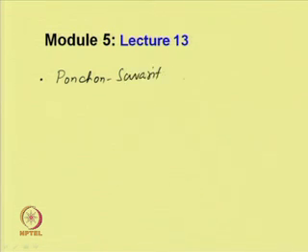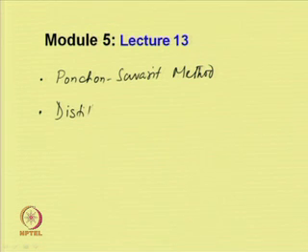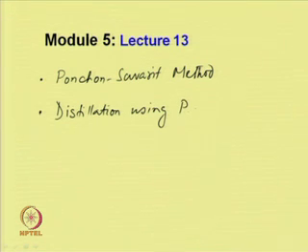Ponchon-Savarit method, and we discussed with an example how to calculate the number of plates required for a particular or specific separation. And secondly, we have discussed the distillation using packed column.